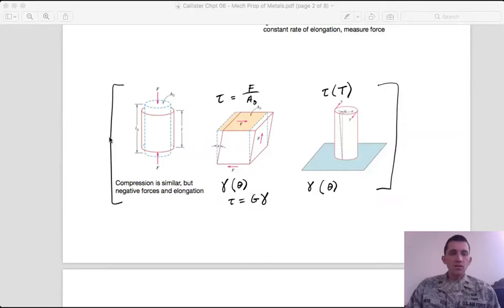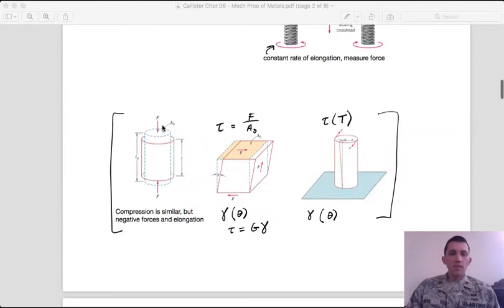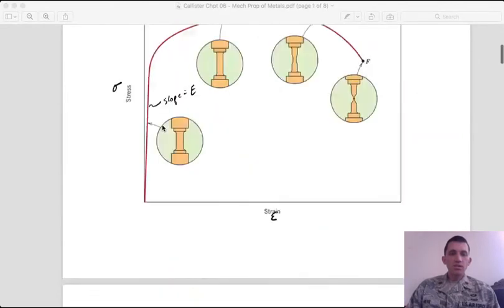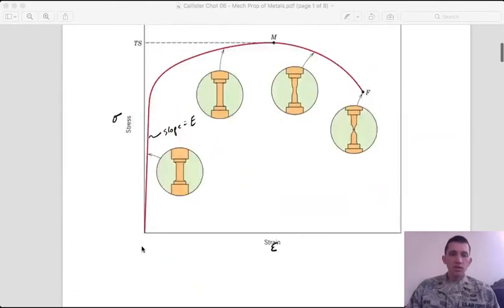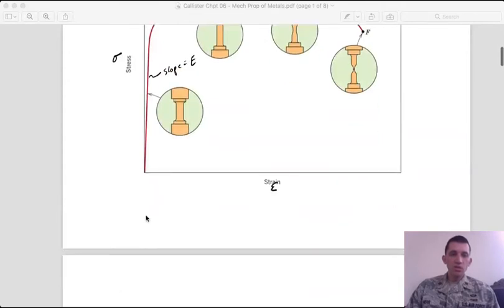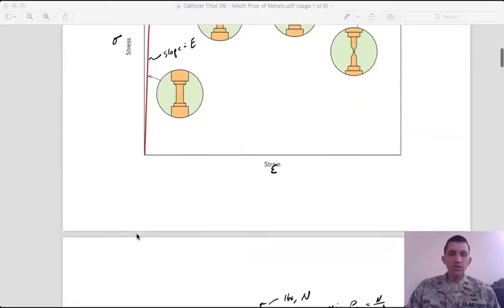And here you can think about, in some cases, the stress strain curve looking similar, just sort of being inverted through the origin. So I would apply a negative stress pointed in the opposite direction, and I would get initially, right, a linear deformation, but instead of being an elongation, it would be a contraction of sorts.